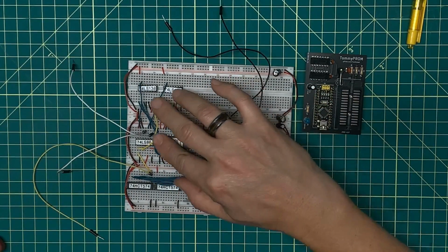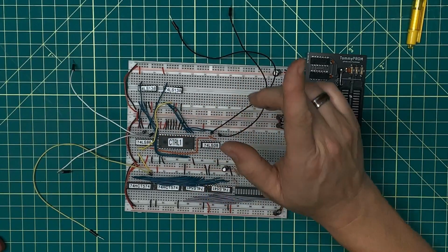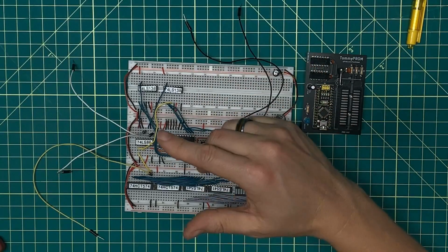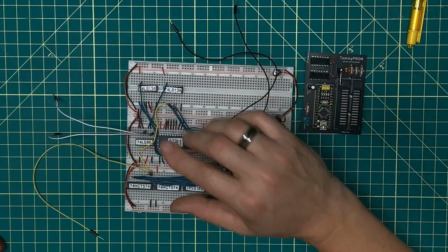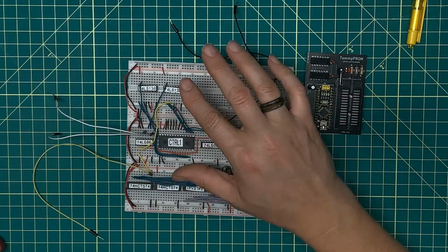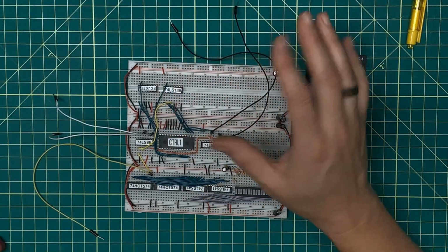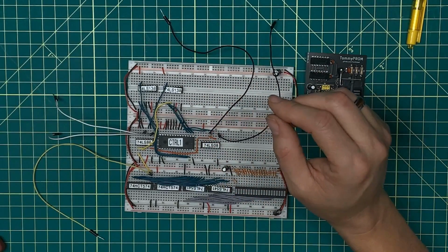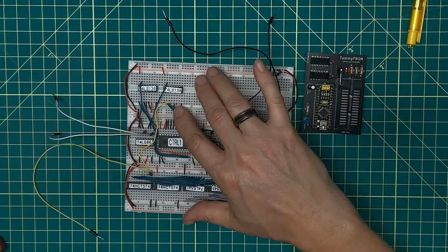I will program this such that every single instruction is equivalent to a no-op instruction. I did not put any LEDs on here to indicate exactly what's going on, and that's because I've got LEDs on the register itself for that, and I didn't want to add anything more to these signals. The LEDs on the actual register are buffered with a line driver, so that will make that a little bit more robust so I don't deal with power problems or LED draining power on the signal lines. So that'll be what's next, is I will take on getting this programmed, getting the code for this written.